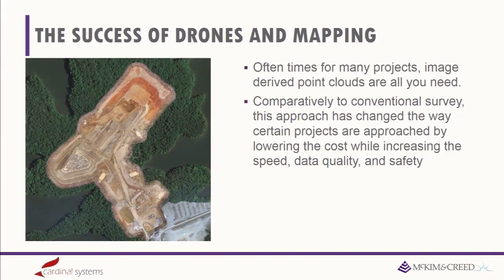So, as everyone knows, unmanned systems have truly been disruptive in the survey and engineering market. The image-derived point clouds, these bearer types applications, have definitely changed the way we approach earthworks projects like this. We can collect the data very quickly. A lot of times we can get in there and collect all the information in a few minutes to an hour versus having survey crews out there while they have all the machinery and putting people in dangerous places.